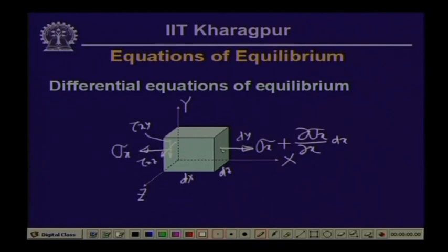Likewise, we will have the shearing stress component tau x y, which varies from this end to this end, as tau x y plus del tau x y by del x times dx, over the length dx.